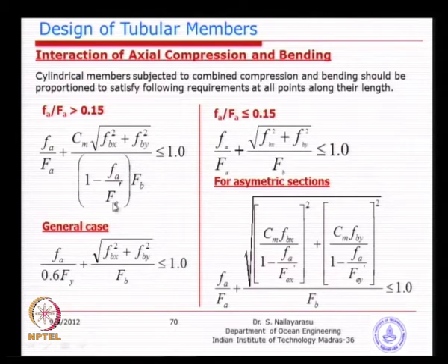So, you look at the bottom part, especially the allowable bending stress, everything else is the same, except here we have a 1 minus something. As long as your applied stress, especially the axial stress, is larger, the deduction factor for allowable bending stress is coming down. The reason is the magnification of the moment becomes larger and larger because of this bending, and we need to reduce the allowable bending stress. This we call the moment magnification factor, which is lying at the bottom.